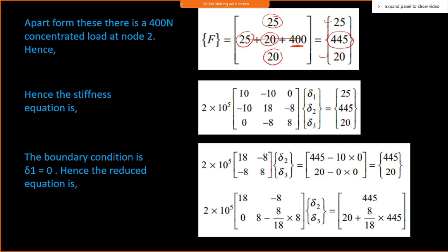And this is the total. Now we can write this into the force vector. This is the force on node number one, force on the second node, and third, like this. I can now substitute into this final equation, this stiffness equation, and then apply the boundary condition. That is basically the procedure to remove, since node number one is fixed. So this is fixed. Obviously, I need to remove this equation. That is what Gauss elimination is called. I'll remove this, and this much part will be used for the solution.